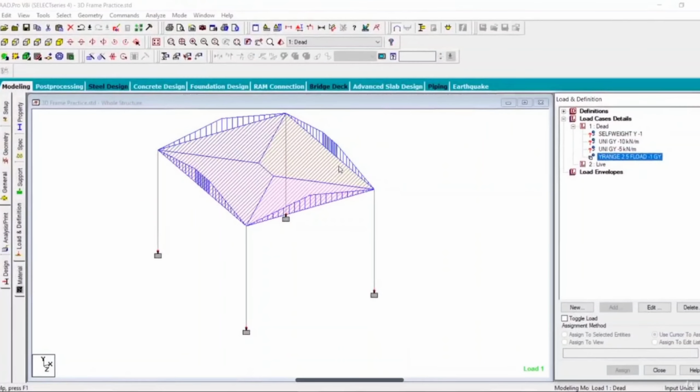The ultimate goal of defining this slab is to transfer the load on it to the beams, isn't it? The same thing is done by STAAD Pro without even defining the slabs. Due to this reason, we do not define the slab, because defining the slabs is very complicated and takes a lot of time, and that is why we don't model the slabs in our regular building projects. You can see how the load has been transferred to the beams.